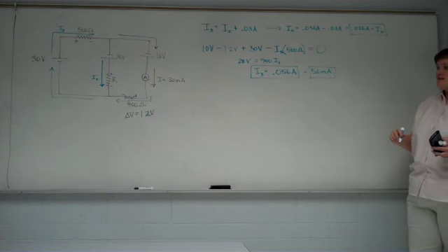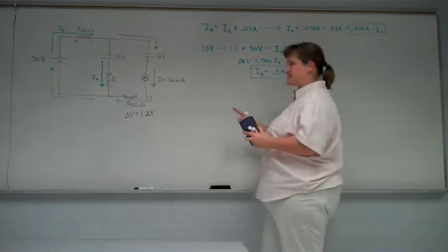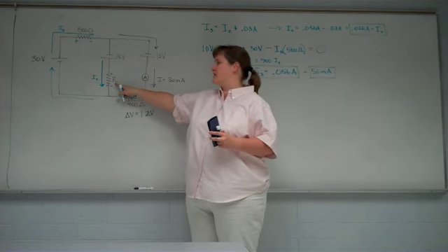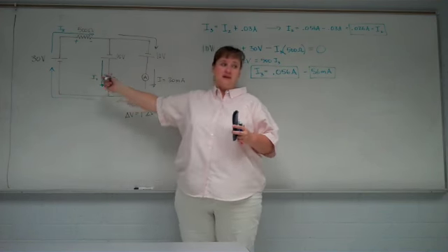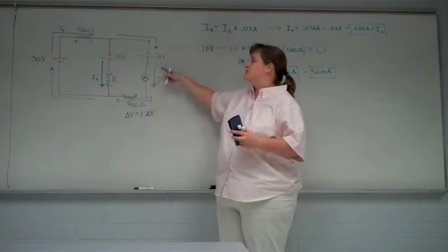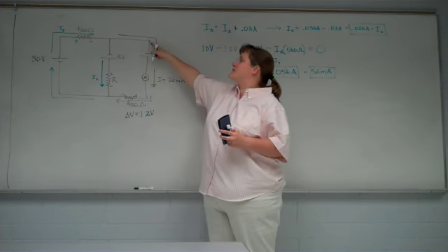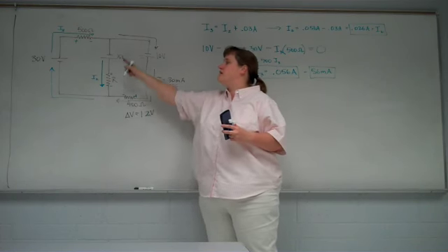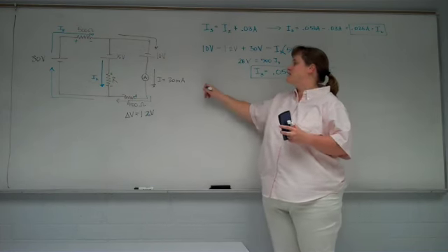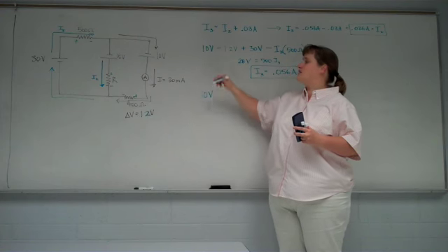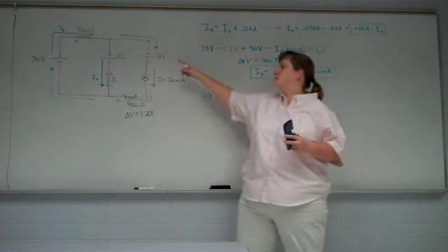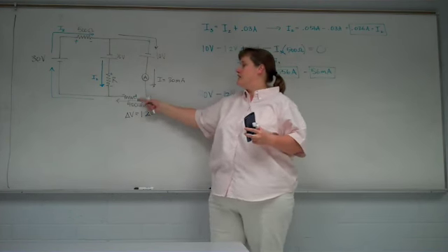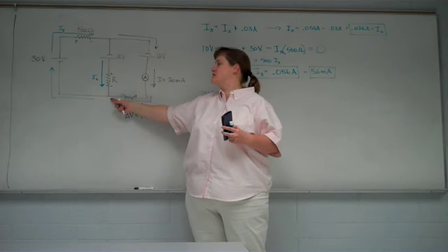Now to find the resistance. To find the resistance, R, what this resistor value is, we need to do either the right-hand loop or the left-hand loop. Doesn't matter which one. If we do the right-hand loop, let's start in the same place and go down again, but this time we're going to come up through the middle. So we still see a gain of 10 volts. We still see a drop of 12 volts. So 10 volts from the battery, a drop of 12 volts from this resistor.